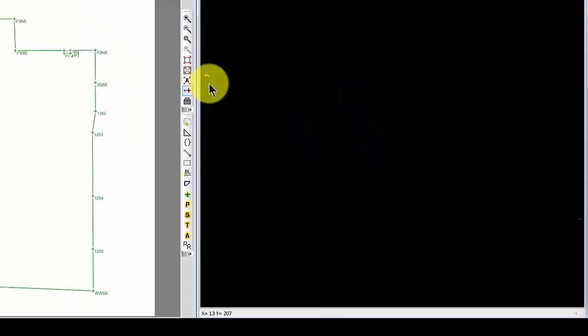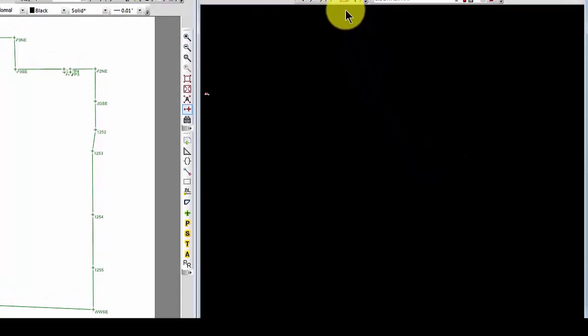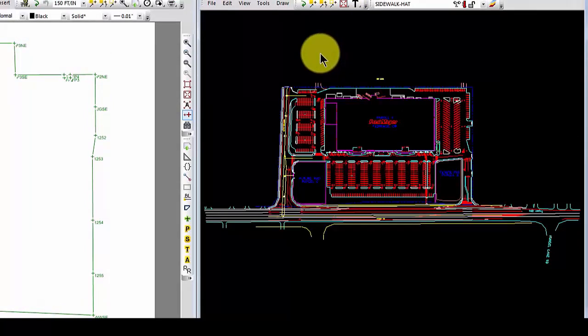And if you look real closely, the survey part I'm interested in is right over here, but I've got some extra stuff that was in that DXF file. And this happens sometimes because there's lots of programs that would write DXF files and sometimes kind of have extraneous stuff. So I'm just going to come over here and select those objects and delete. That allows me then to come in and do a zoom extents and really see the information that I'm after. And you can see that my coordinate system is rotated in the CAD drawing to the right. So north is to the right in the CAD view. North is straight up in the drawing view.